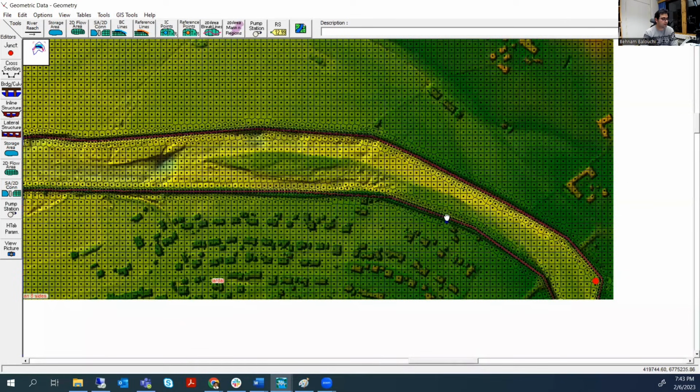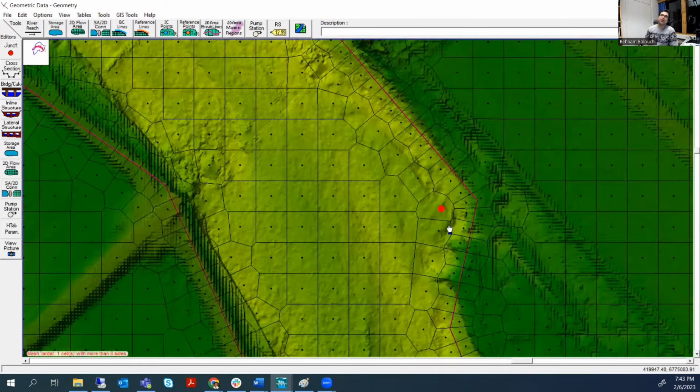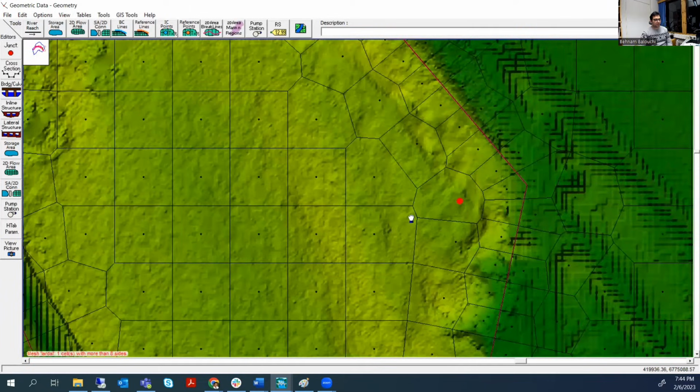It defines one important thing for the HEC-RAS mesh. It is really important that you don't have very small edges like this one. It is better if your mesh cells are between 4 and 6, like rectangular, but you know, these small edges are not good for HEC-RAS and you get an error for that.